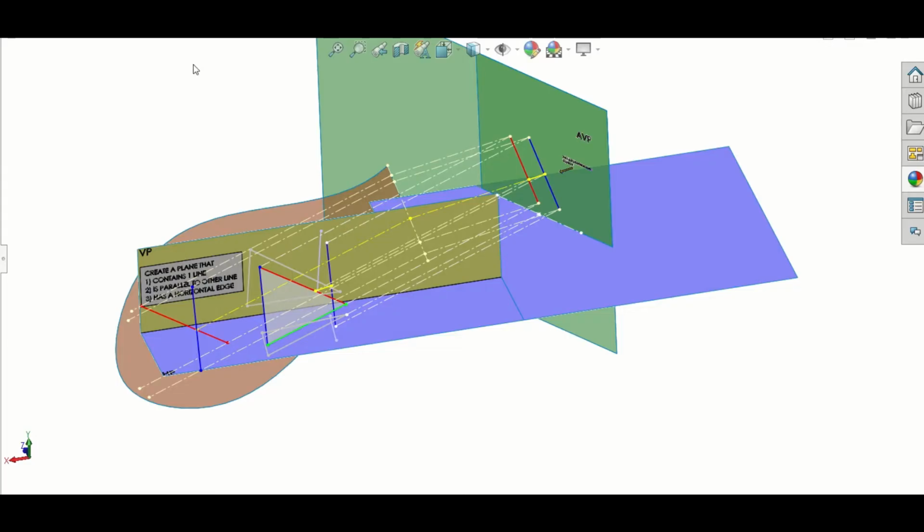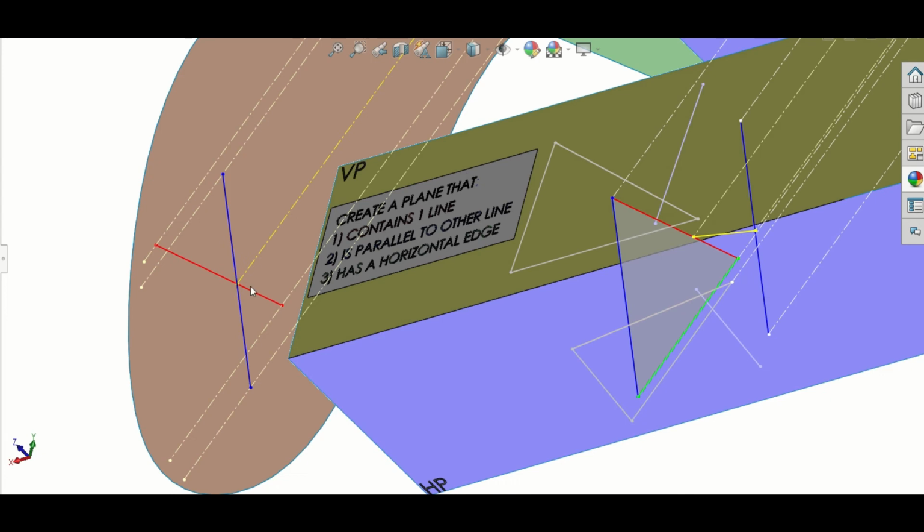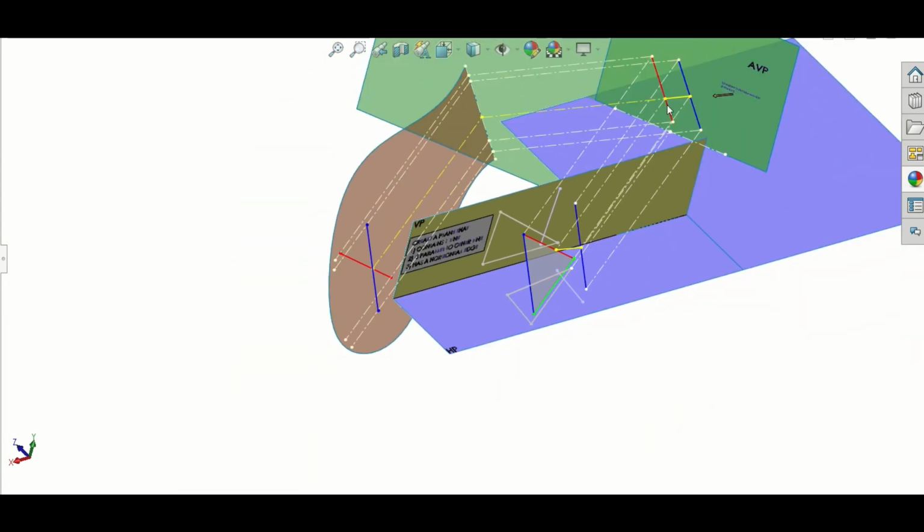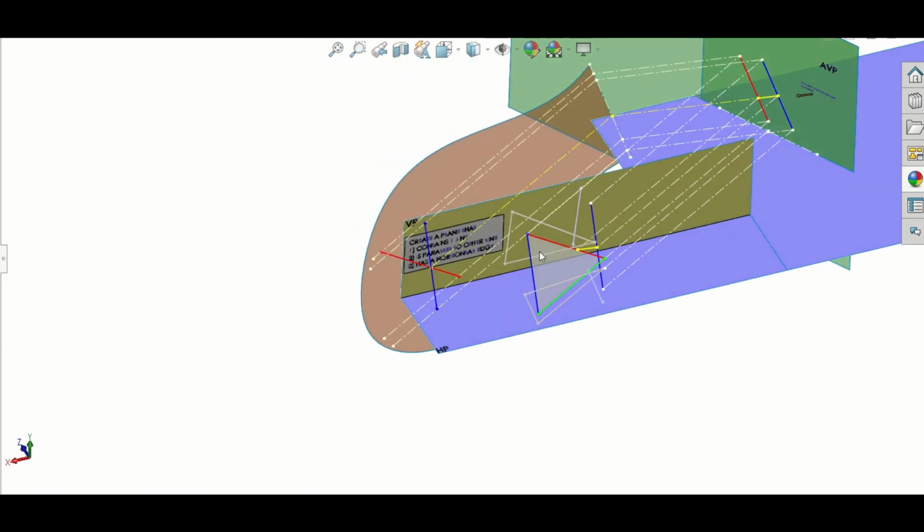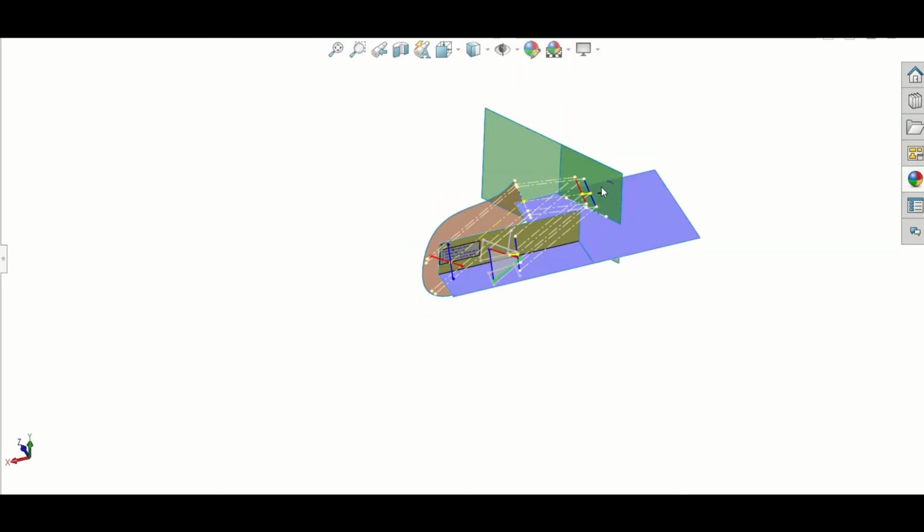Now, as I mentioned previously, we have to base everything on this view here, which shows the two lines appearing as parallel. If the question was posed shortest distance or shortest perpendicular distance, you look perpendicular to the lines, you get your shortest distance from the point view down here, and it's projected back up through the views. And there it is, shown as a true length here in yellow, and shown as it appears in the 3D here, which is just projected up to the elevation, down to the plan, and so on.